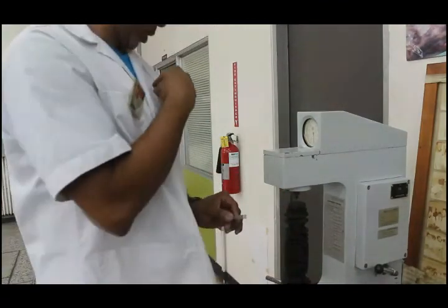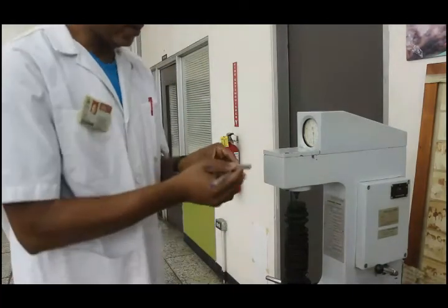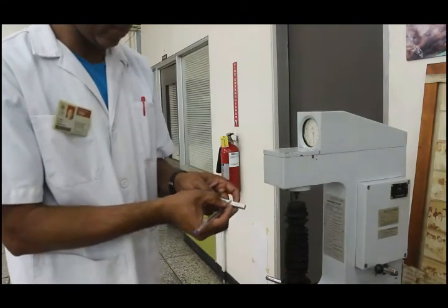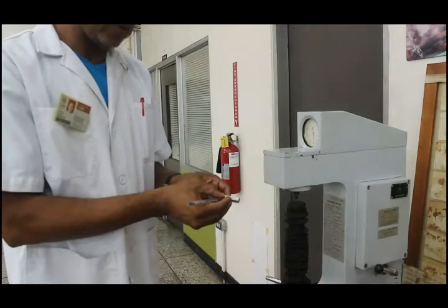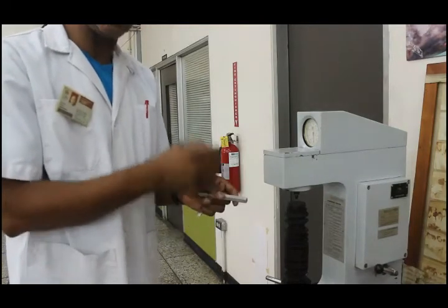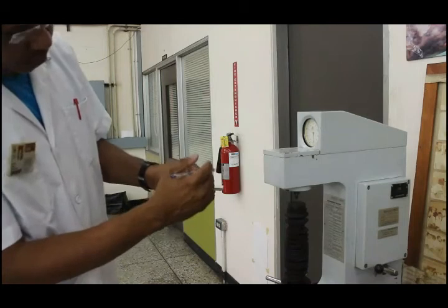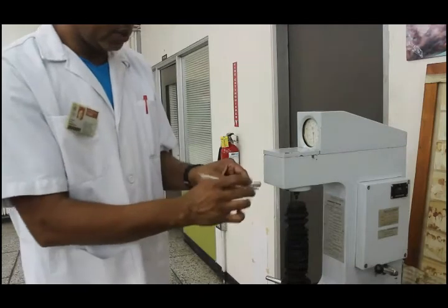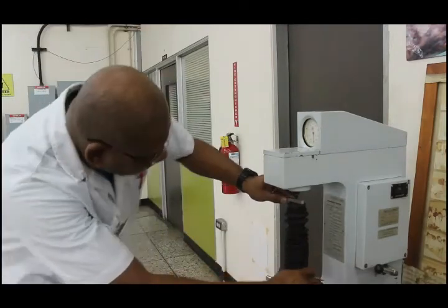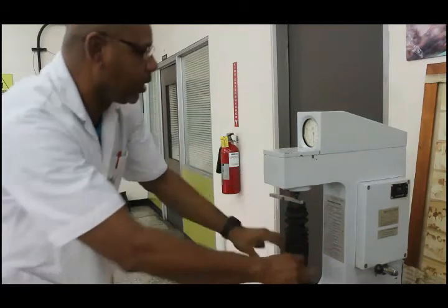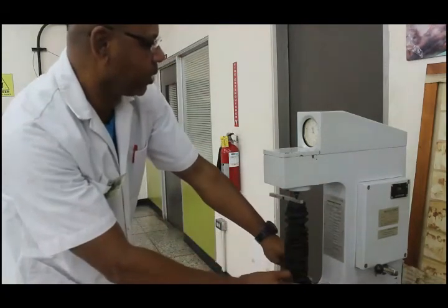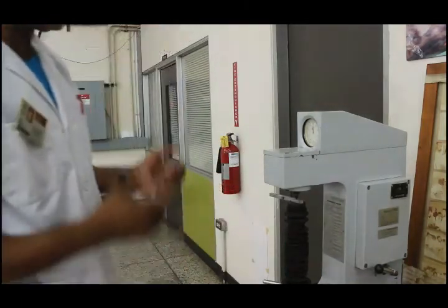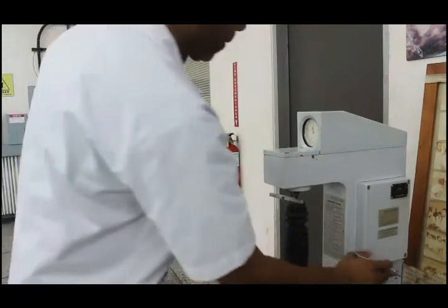What you need to note is that each time you do a hardness test on the material that you have, there's a little indentation mark from the indenter. So you need to shift away from that. As I show you, do not repeat the test in the same area where the properties within this region would have been changed. So you shift your sample to a new position and repeat the sequence. You repeat this sequence on average of 3 times, where you'll be able to get an average reading to determine the Rockwell hardness.